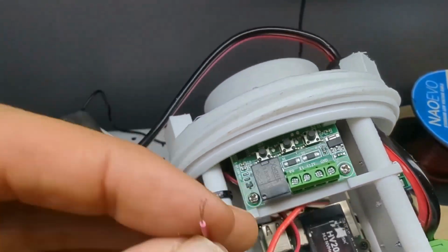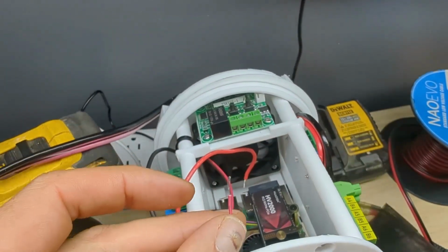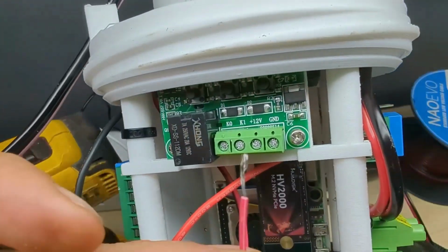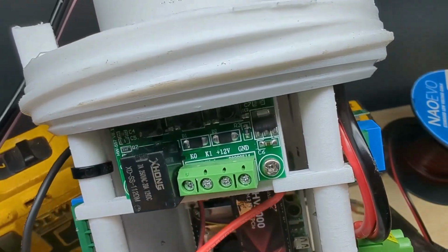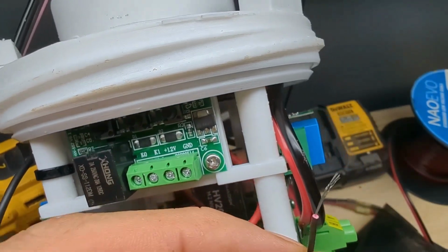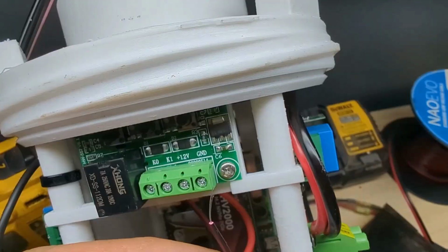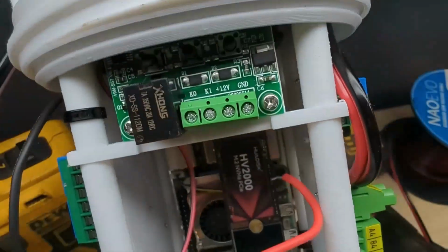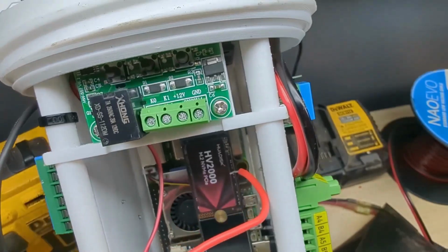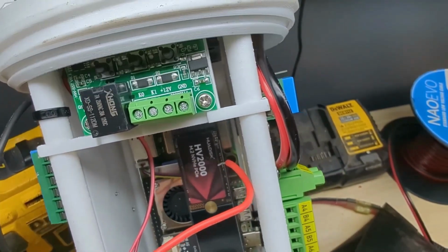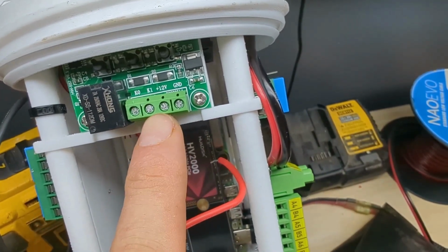So now the fan that's coming off of this is this real skinny red wire. This is going down to the fan. It's going to go into this first terminal, this K0. The ground, obviously, is going to go to the ground side here, but it's also going to share that with our power connector that we're going to run over to our power distribution block. But the unique thing on this situation is these two in the middle are both power.